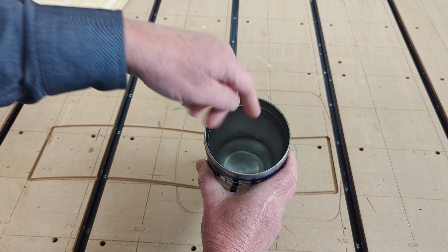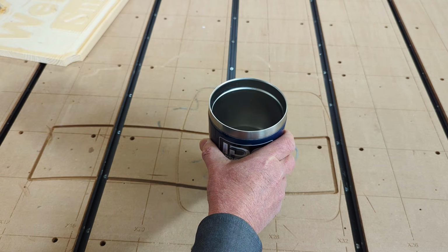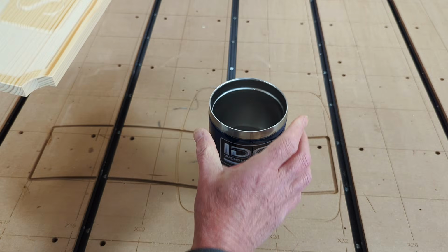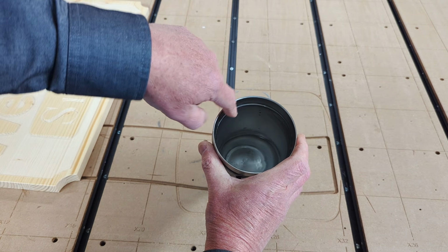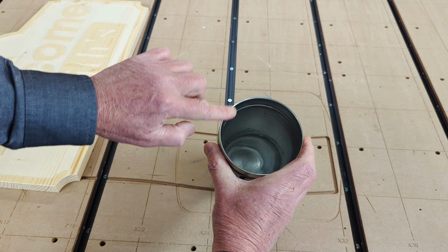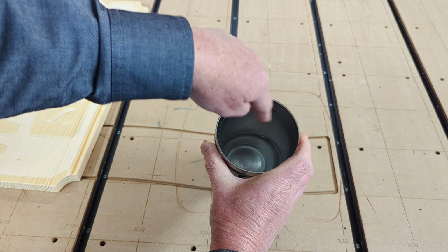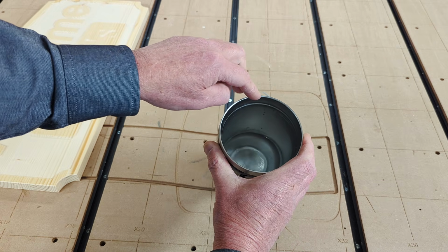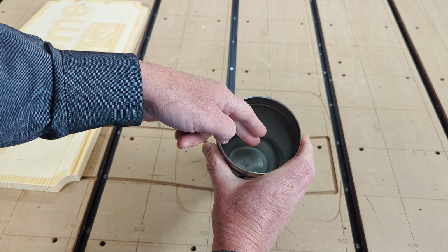And Vectric, when it's cutting a pocket out, which is what that kind of carve is, these recesses that you're going to be doing, these are called pockets. When you're doing a pocket out, the software needs to have a closed vector because it says, I am only cutting the hole in this cup. But if there is a slot there or a missing component or a start point and an end point to that circle, I can't pocket it because it is an open vector. Without knowing the distinction between closed and open vectors, when you're generating toolpaths and the software tells you it can't do that, you're not going to know what to do to correct the problem. And that's why this is so important.